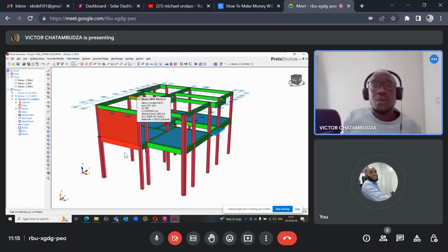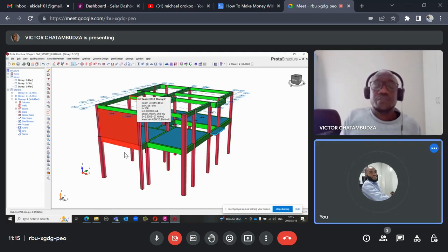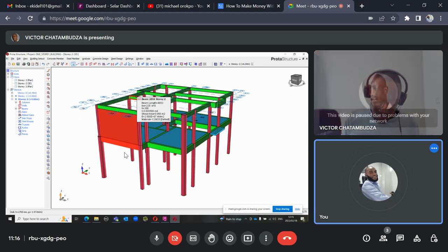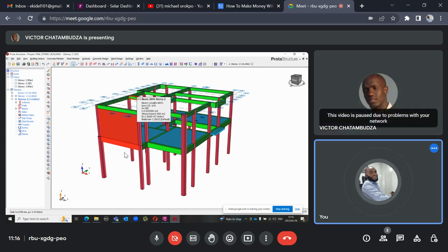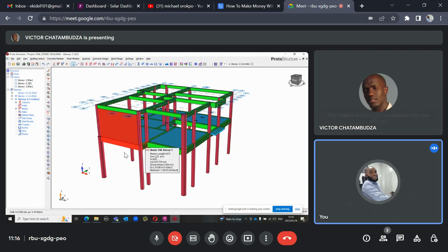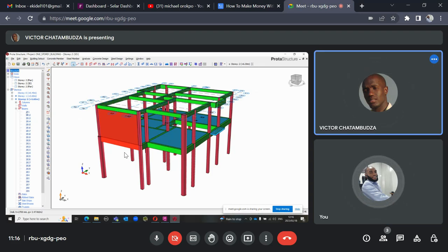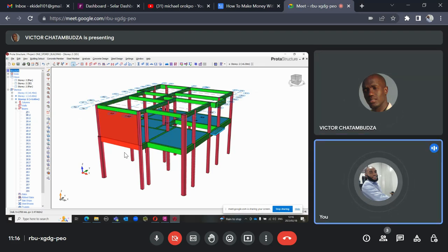So right now on your tree, make your beams display on the tree. That plus sign on the beam, drop it down so that I can paste it on all other beams. On your tree, I mean the left hand side. Now click on the first beam, the one that says 2B1. To select your beams, hold your shift key and click on the last one.